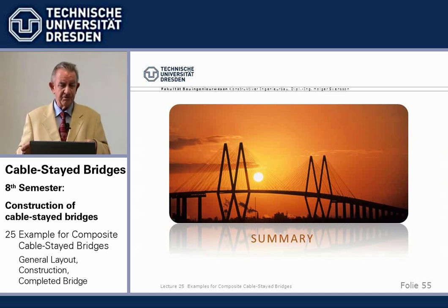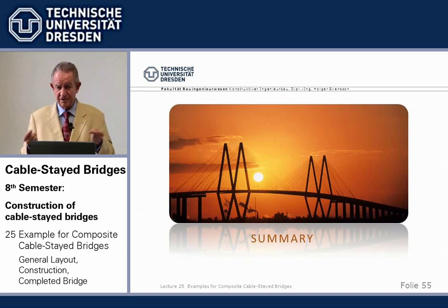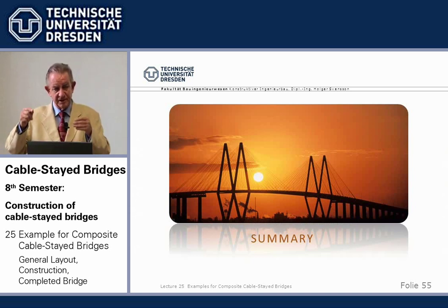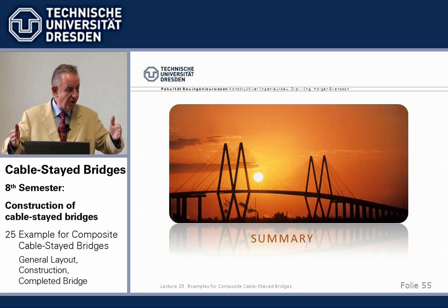The alternate, which I found is more economic, is to use a deck from precast slabs resting on the cross girders, cast in place joint, which are certain disadvantages, but because of the natural compression from the stay cables, they are under compression virtually all the time.